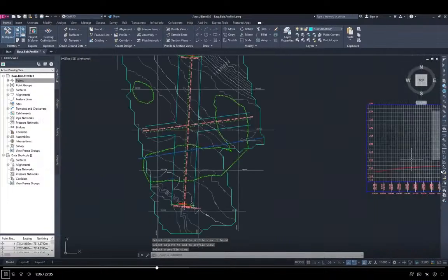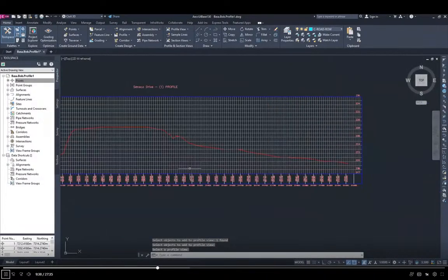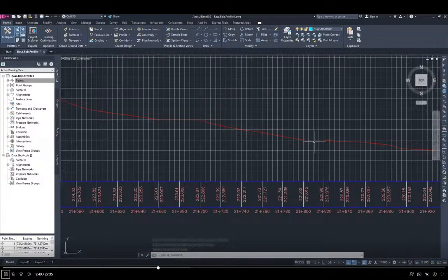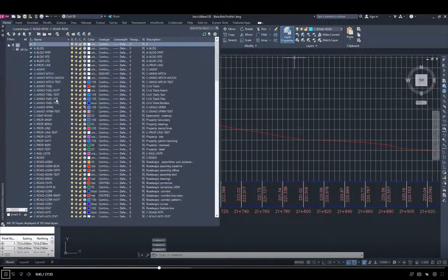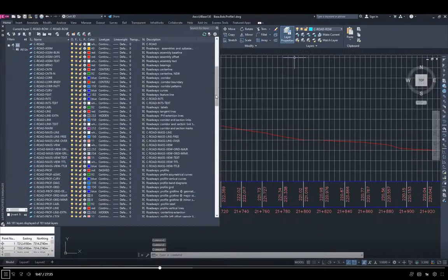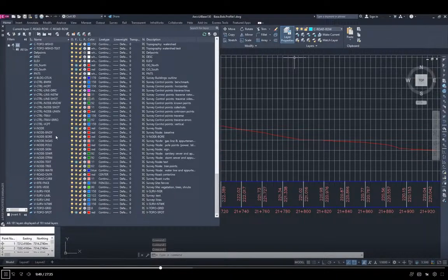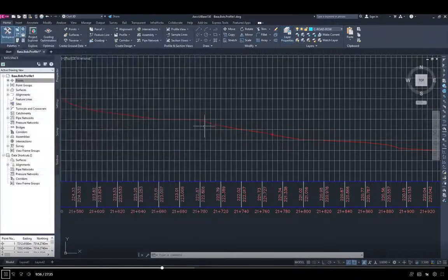Now the point should appear somewhere here, but if you notice, it's not appearing anywhere. That's because it's on a layer that's frozen. So we're going to unfreeze that. I'm going to open the layer properties, and we're going to go to vNode. That has to be unfrozen. So we unfreeze vNode right here. And if you did everything like that, there's our X.